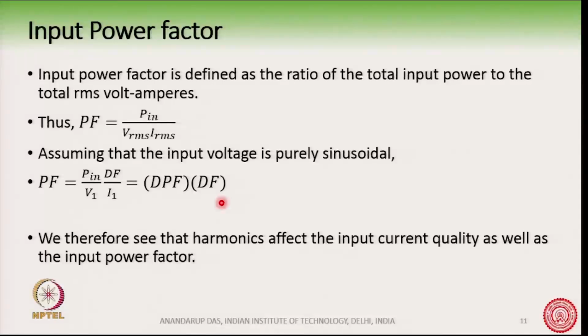This relationship is noted because the effect of harmonics is not only to distort the current; harmonics also deteriorate the power factor. So harmonics affect the input current quality as well as the input power factor. Therefore, we need some methods to address this issue.